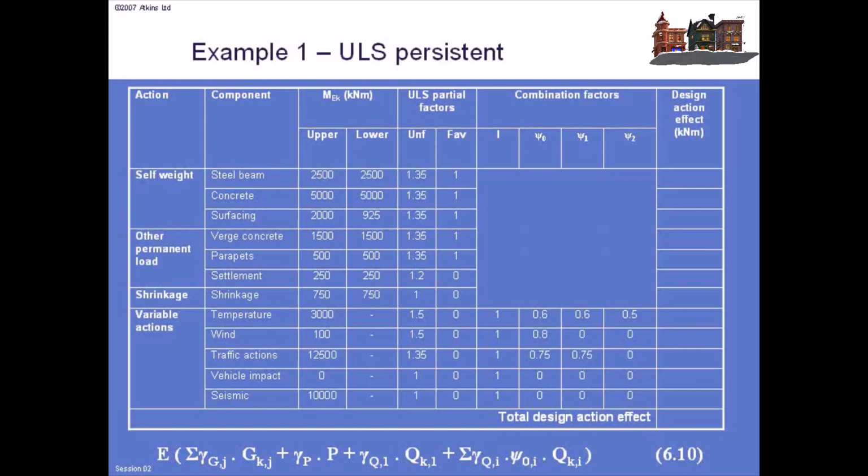And they've also filled in all the combination factors, psi0, psi1 and psi2, again, from the Eurocode. So that's basically all the data in there, but we then need to use that data to perform different load combinations. So if we're interested in the biggest bending moment in the ultimate limit state combination, then the formulation at the bottom of the screen there is the one we've got to use to calculate what the bending moment is.